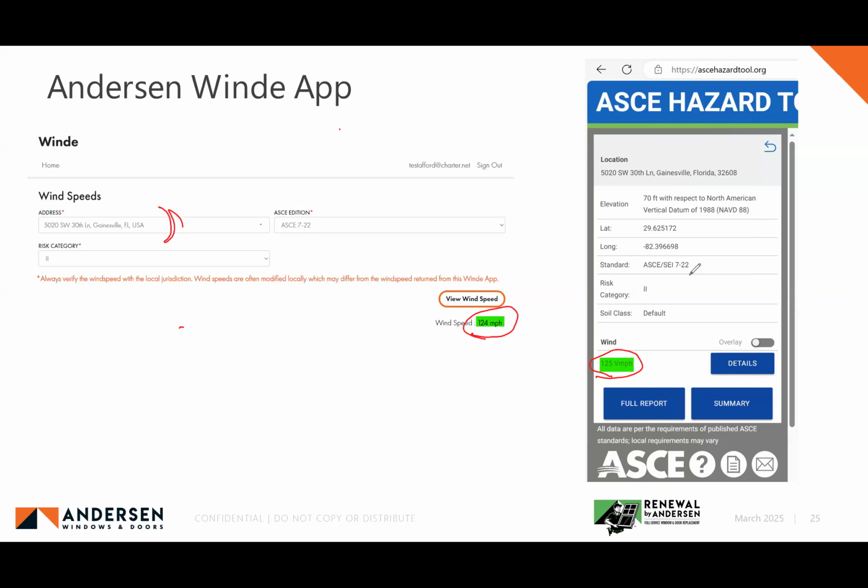As you can imagine, these databases don't have every single point house located within the database, but the wind speed contours on the map are geolocated, and then each of these wind speed databases uses an interpolation algorithm to interpolate between the contours. So they are a little bit different. ATC gave you a little bit different wind speeds than ASCE 7 did as well.